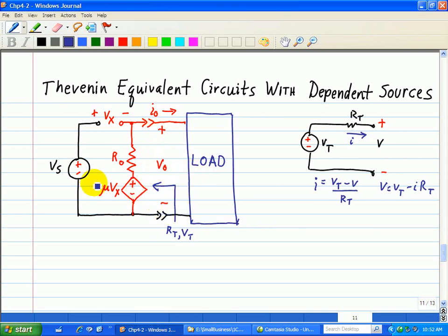So looking back at this circuit. In this circuit, the controlled voltage Vx appears across an open circuit between, let's say, nodes A and B, as I labeled here. And by the fundamental property of node voltages, we could see that Vx is simply the difference between the voltage at one end at node A and at the other end at node B, but that's just VO.